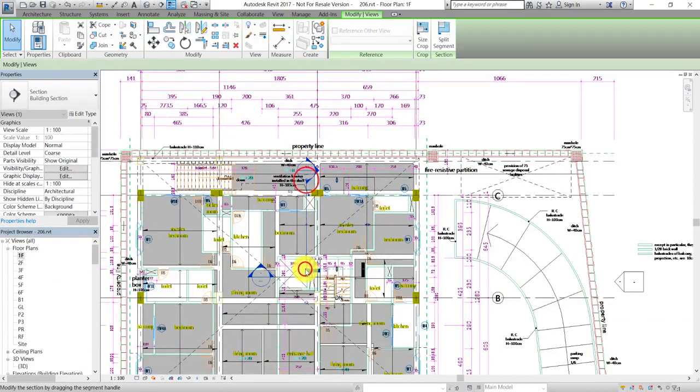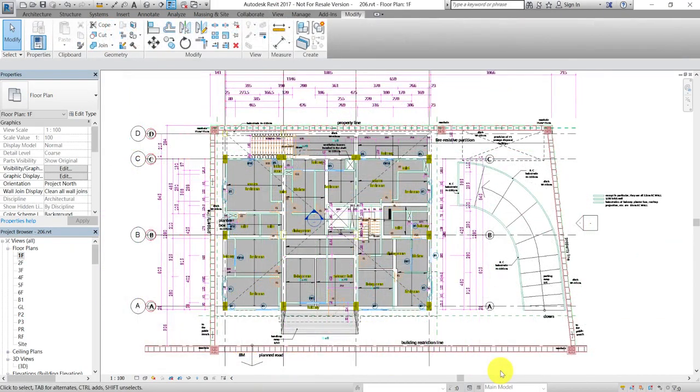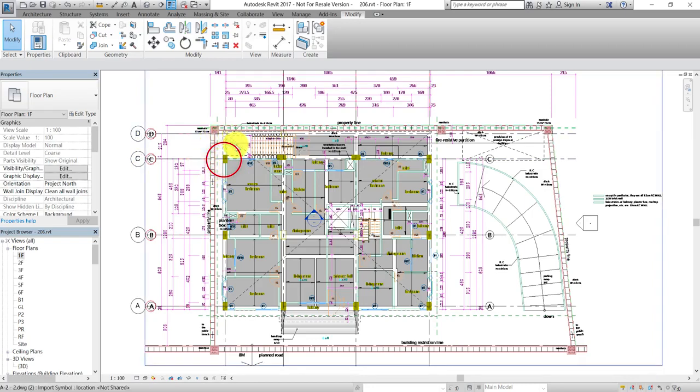How about splitting the face of a column? The split tool can be used to split the walls. However, it does not work for the columns. Let us use another approach to achieve it. We may attach a thin wall on the face of a column first, and then paint the thin wall with the material needed. Let us take the column located at the northwest corner, for example.